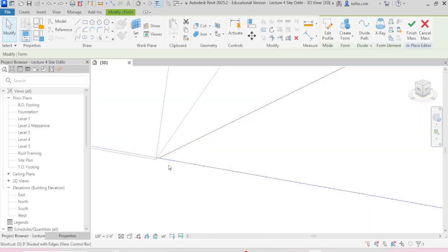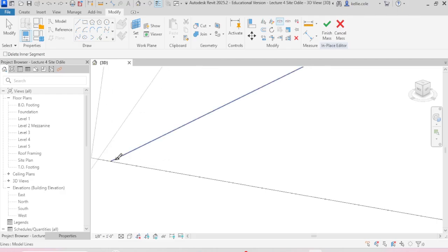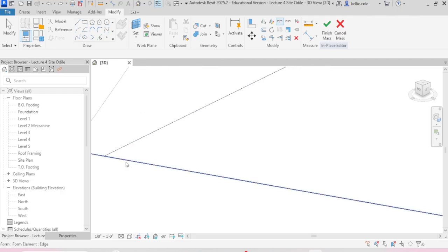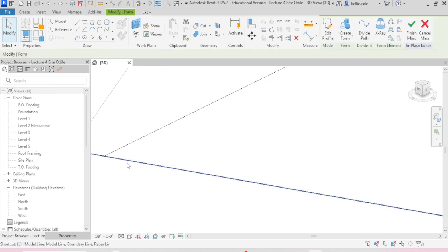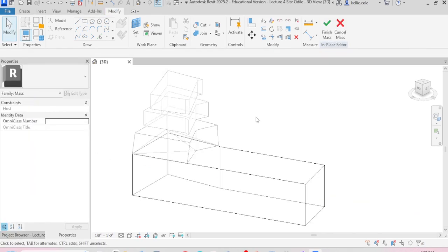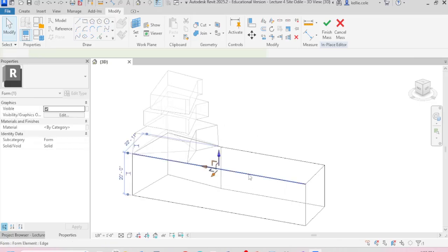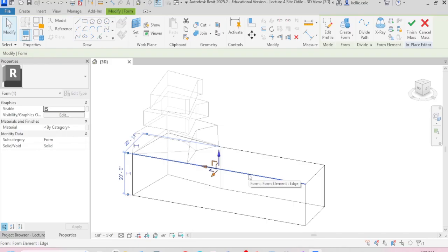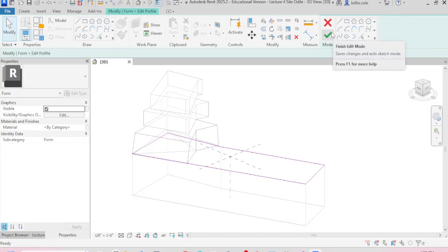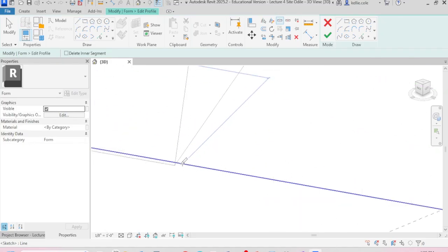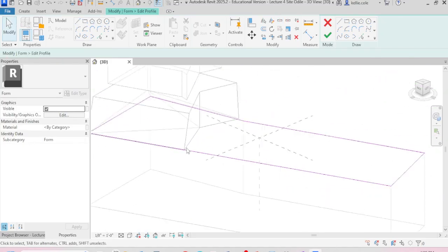If you want to slice lines at any point, you can use the SL Slice Line tool. And if slicing doesn't work for you, it didn't work for me while I'm in this command, we can always edit the profile. So we'll go one layer deeper, edit profile after selecting that line, and try slicing within that at the intersection of the mezzanine.